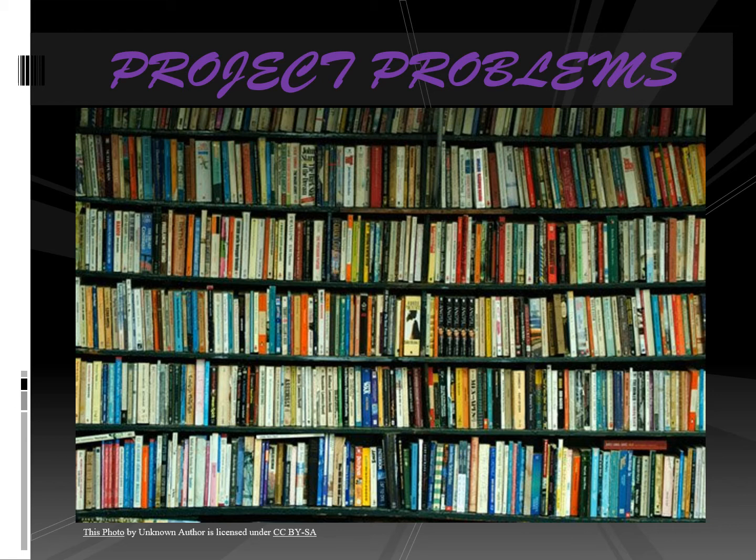Problems arise when scanning fillet welds with conventional ultrasonics or phased array ultrasonics due to the lack of Australian standards available. At the current time, there is no Australian standard that gives guidance on the testing requirements or acceptance criteria. Australian Standard AS 2207 is the standard used for ultrasonic testing of fusion welded joints, which can be used as a guide when conducting PAUT, but doesn't actually mention phased array at all.